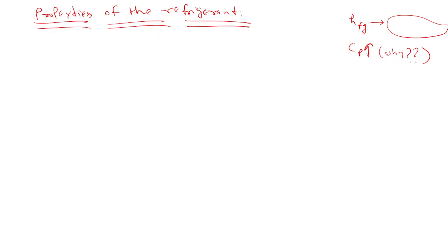But generally you absorb heat in which zone? Constant temperature zone. So why are you going for this? Sir, h_fg should be high, right? Okay, h_fg is high. Then would Cp be high or low? Cp will definitely be low. Yes, sir. Why?